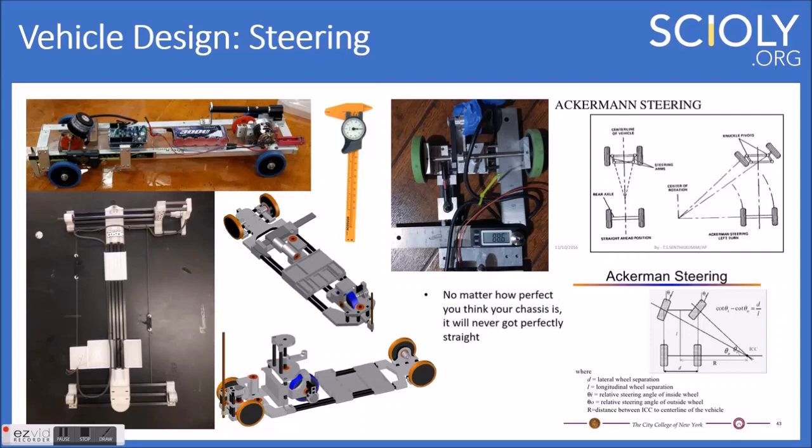And I do know one team that actually successfully did implement this, being able to turn, but I think they had some problems at nationals and they weren't able to. I believe it was Acton Boxborough, but they didn't end up pulling it off. It's very, very difficult. I would really recommend the fixed curve whenever you have a curved scenario. You can see this Ackerman steering. You can do this fixed curve or have a servo there for that. And so it's a little bit more complicated. It might not be completely necessary, but it's going to minimize any slip problems that we'll talk about later.